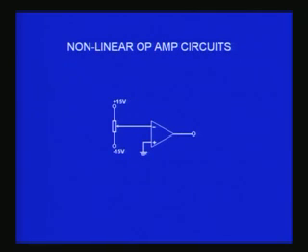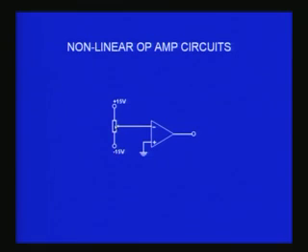Now, to show precisely what I have done, I have shown another simple circuit where I have got a potentiometer which has got 3 terminals. One terminal is connected to plus VCC, plus 15 volts, and the other terminal is connected to minus 15 volts, and the wiper, which corresponds to the variation, is given to the inverting input or the non-inverting input as the case may be, while the other input of the op amp is grounded. Now, you know what will happen at the output. Somewhere in the middle of this potentiometer, the voltage going from plus 15 to minus 15 will be very close to 0.